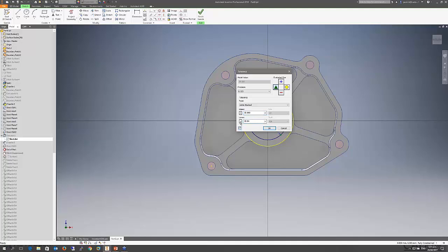In this case, my lower limit is 0.04 over the nominal size, and my upper limit is 0.06 over the nominal size, which is a perfectly legitimate tolerance. They don't always end up that way, of course. You might have a minus and a plus for your upper and lower limits, but the point is we're telling the model that this is our allowed range for that value.